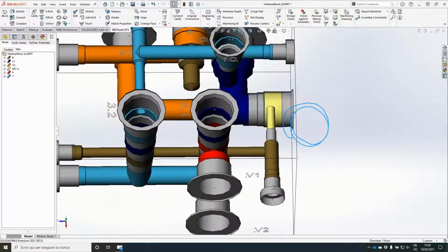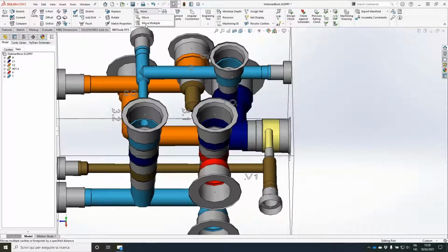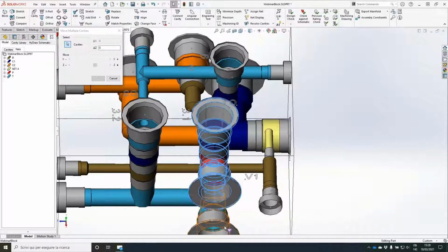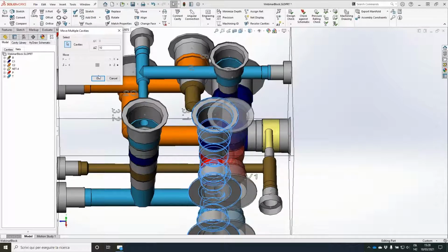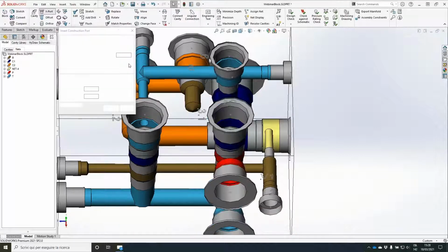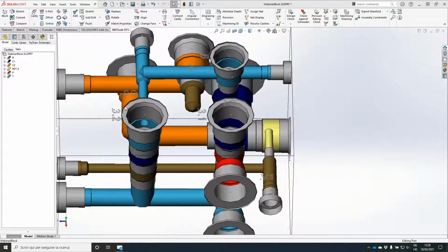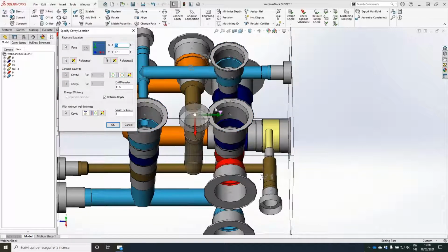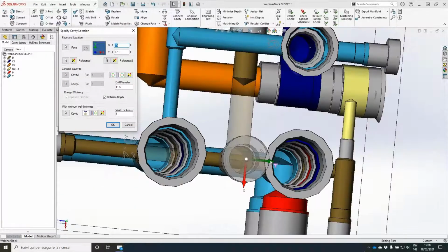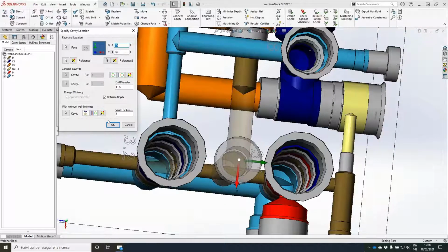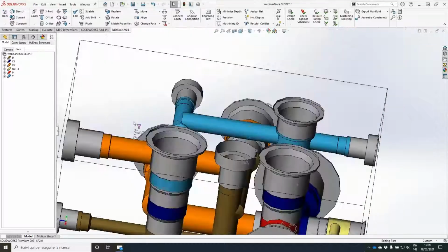And basically, we can see that we have room to make the connection in between. So we can do a move multiple. We can take all these cavities and move them to the right. Let's make it 10 millimeters to the right. Now we can make a construction plug on port 1 and here, and we can take 1x4, okay, and we put it on the top face. There will possibly be an intersection between spot faces. So let's move the green side. And we have made our connection.